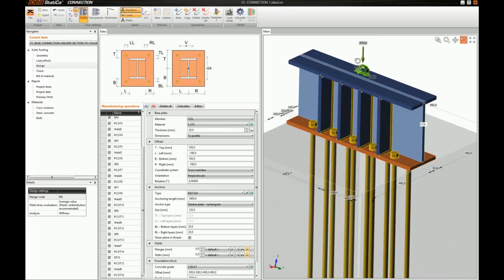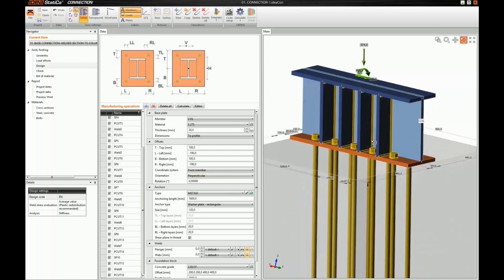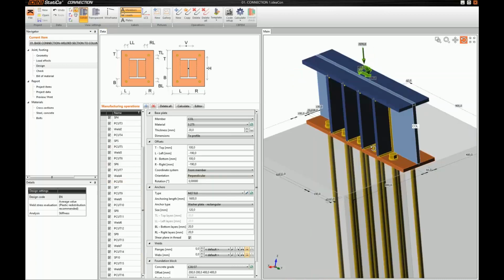And the loading is a little bit awkward because the loads flow through the web of this beam and then are distributed at the plates, which are welded after to shape the I section. And because this is not a standard I section, he had to create all these operations just for the stiffeners.